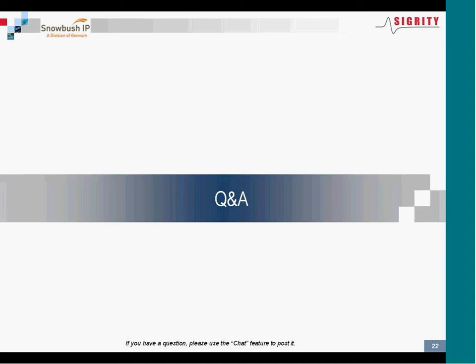No, the way that it works is the actual raw waveforms are folded onto each other and post-processed to create that eye density that we saw in the demonstration. And from the eye density, which will include whatever crosstalk is in the system, as well as any jitter injection that you've injected into the analysis, that eye density will be post-processed statistically using industry-standard dual Dirac methods to do the extrapolation and produce the bathtub curves.